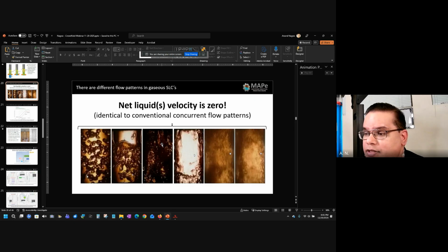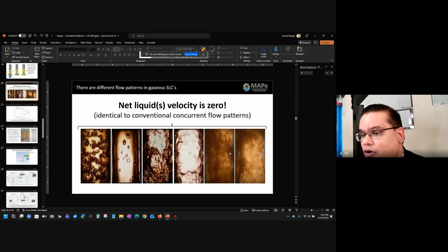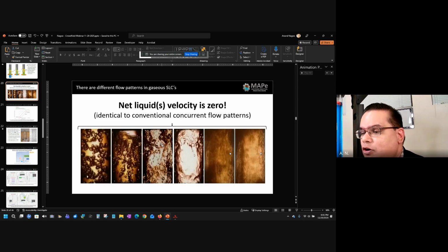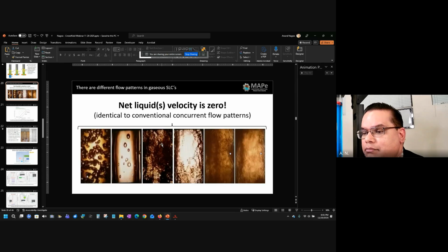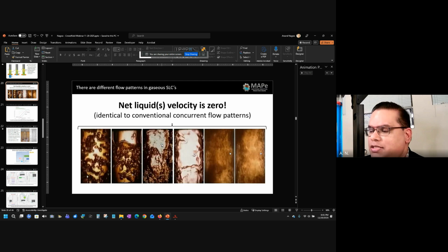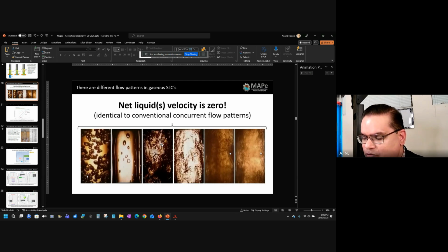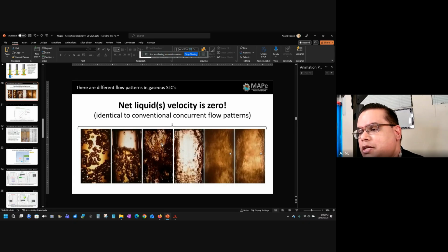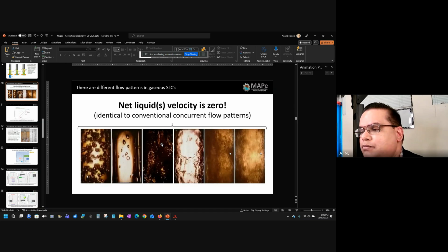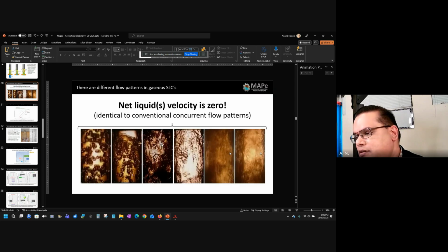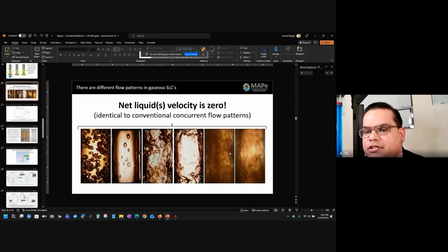Intermittent gas lift is all multi-phase flow, right? It's all static liquid columns, right? And the ability to understand that fallback, because it's a liquid column. Before you even get the opportunity for the pressure to remove that column, you have to understand the liquid column that's forming. So I would imagine that those people who are focusing on intermittent gas lift, this would be an incredibly important technology to take advantage of.